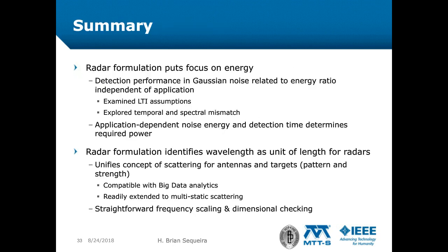So we have examined a radar formalism that emphasizes the work done to detect targets. This leads us to the concept of energy expended to accomplish the function of detection, which acquires the sub-functions of target illumination, echo reception, and computation. Of these, we've examined only the role of illumination in detection and see that for a Gaussian noise, knowledge of energy ratios is sufficient for realizing a given detection criteria specified by P sub FA and P sub D.